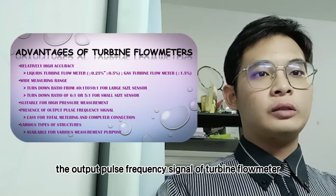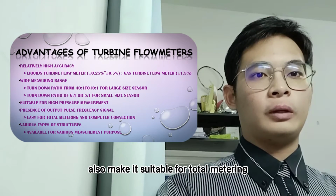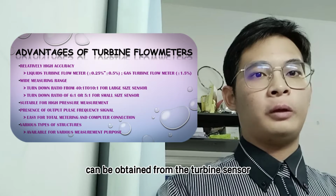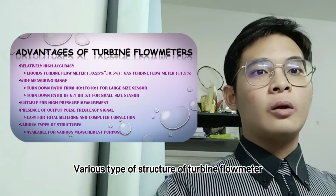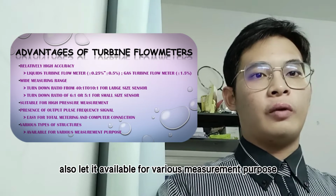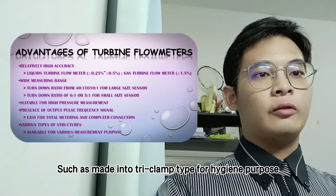The output pulse frequency signal of the turbine flow meter also makes it suitable for totalizing and computer connection, as a very high frequency signal can be obtained from the turbine sensor. Various types of structure of the turbine flow meter also make it available for various measurement purposes, such as being made into a tri-clamp type for hygiene purposes.